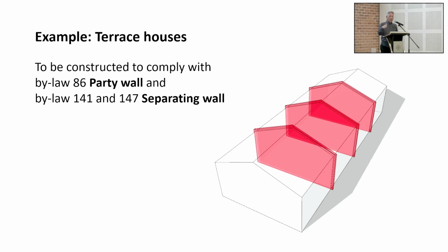Okay, so for a house, the only fire rating you talk about is that of the party wall. So you have to construct it as a party wall. That means you cannot allow any structures to go through. All your roof structures, everything must terminate. You cannot share your neighbor's water. You cannot have the neighbor's water pipe going through his house and distributing to your house. You cannot have the incoming electrical cables going from the end lot corner house right through all the party walls to distribute it to your house.